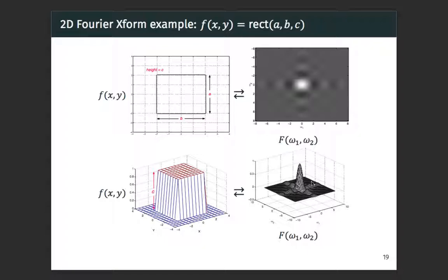All right, so remember, this is something you've seen in 1D. Here, the pulse has a massive discontinuity. When you go from here to here, there's a sharp discontinuity, and therefore what you can expect in the Fourier domain, the frequency domain, is a big mess. You're going to have frequencies spreading to infinity, frequencies at the highest number you can think of.